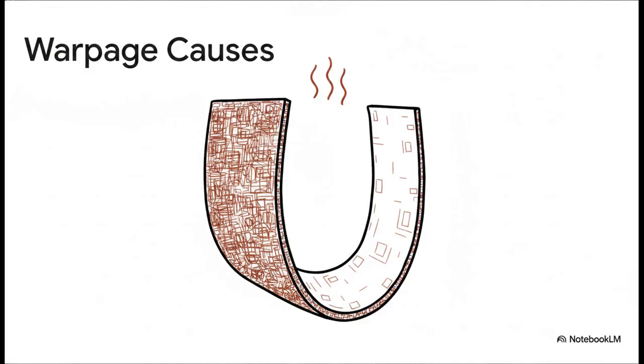The root causes here boil down to severely unbalanced forces. Beyond just the CTE mismatch across core materials, if the copper routing traces aren't perfectly balanced symmetrically across the substrate layers, the whole package is going to warp dramatically under thermal loads. And those thin substrates we use today, they are especially vulnerable to this relentless flexing.